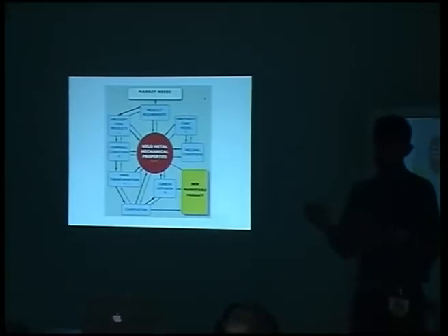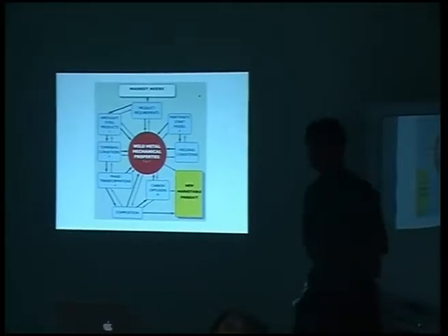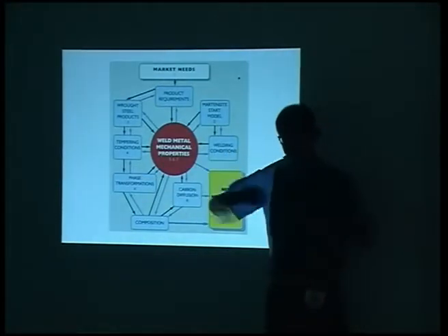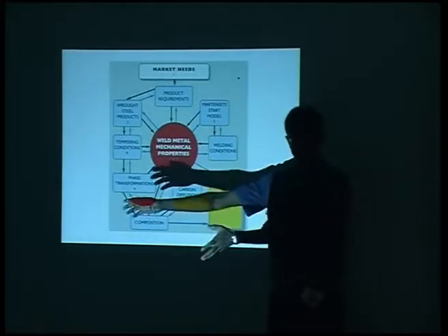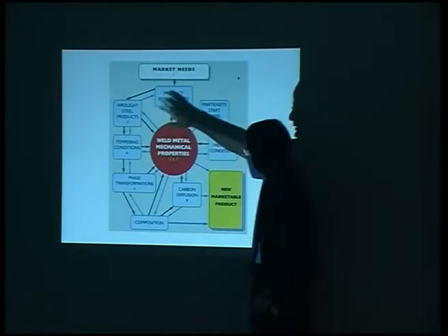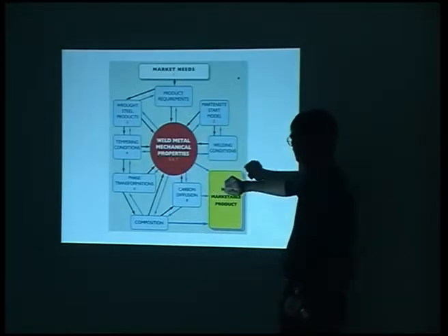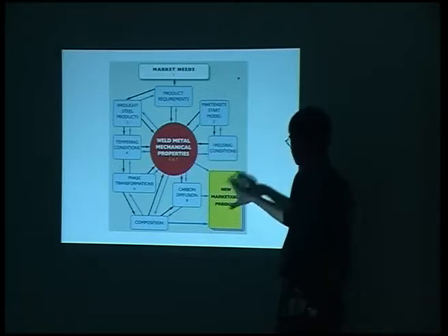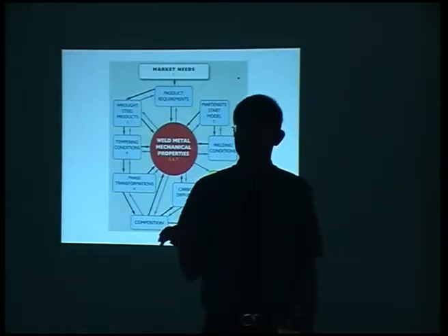This is a project in which, over a period of 3 years, we had to design a welding electrode for a particular need in a power station. So the need was identified by the market really, that we needed a welded rotor instead of a continuous rotor. Because in one part of the rotor we needed toughness, in another part we needed creep strength, and the two steels were incompatible. So we created a whole set of models, including microstructure, tempering, working with industry. And the idea was within 3 years to come up with a marketable product. Okay? So it wasn't a case where you could try out many different alloys and so forth, because testing takes a long time.